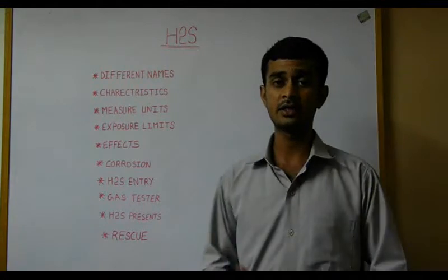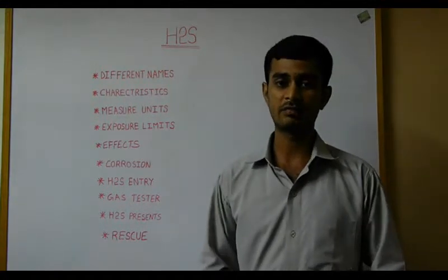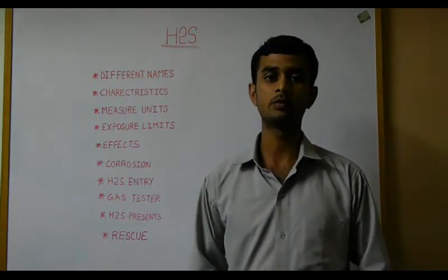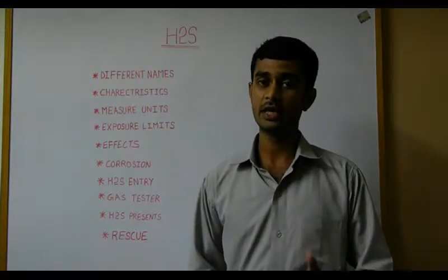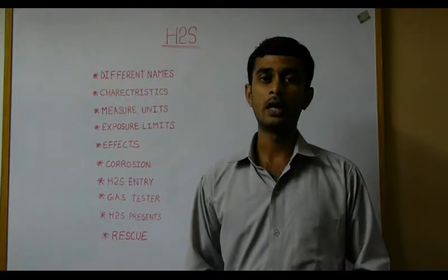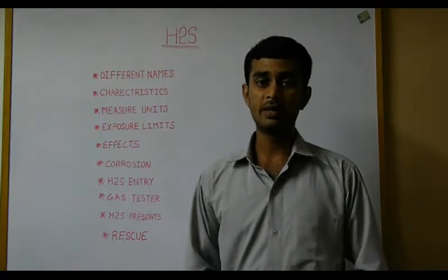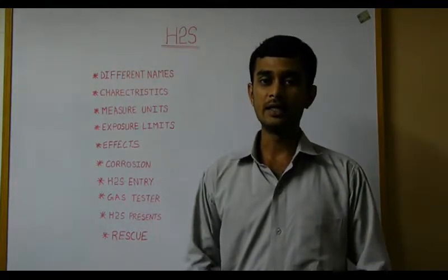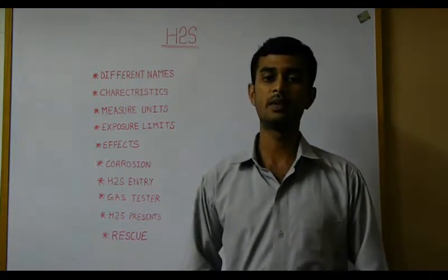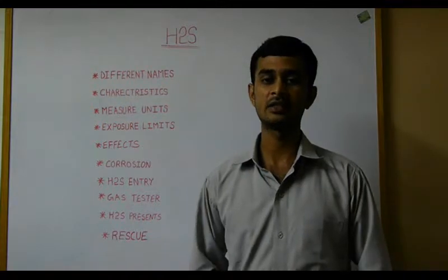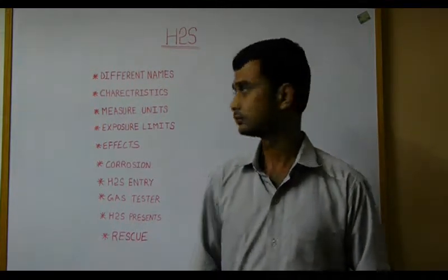At higher concentration levels, from 50 ppm to 200 ppm, severe respiratory damage, irritation, shock, coma, inability to breathe leads to death. When concentration increases to 300 ppm plus, rapid death may be the result.